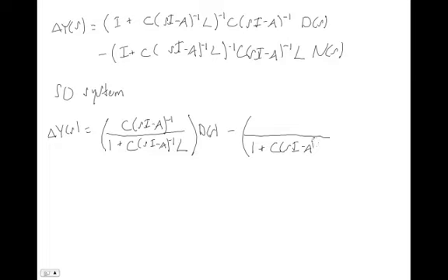And you get these same denominators because the characteristic equation of your system is always invariant to the types of signals that you pass through it. So, whether your system is fundamentally stable or unstable, that doesn't matter which signals you look at. You always get this same characteristic equation, the denominator. So now we have (sI minus A) inverse L. So this is the transfer function from noise.